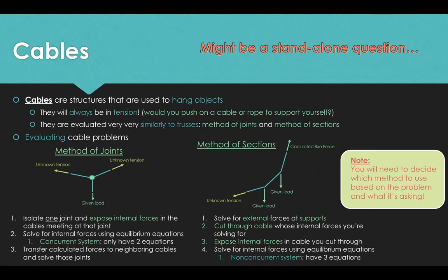Okay, and one more thing, sorry. Would it be wrong to assume, let's say in that method of sections, that if you were to complete the cable to the left, both ends are basically at the same point? Would it be wrong to assume that the force in the X direction are both 0? I think that's what the problems were saying. I just don't want to get mixed up. It's weird with cables because you're talking about the reaction forces, right? Your reaction forces are always going to be parallel to the member that first comes off of the wall.